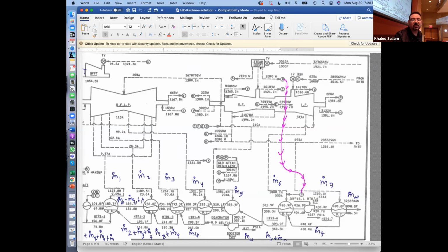And then where do you go? This is the steam chest. It sends you to the high pressure turbine. And then you leave going to the reheat. But before you send everything, you take some and you take them to M.7. What's that? That's the last feed water heater before the boiler. But the rest, which is now 2.8 million, goes to reheat and comes back. So we go to the boiler twice. We go as water here and you come back as steam. And then you go back again as steam, but not that hot, so that you can get reheat and come back very hot.